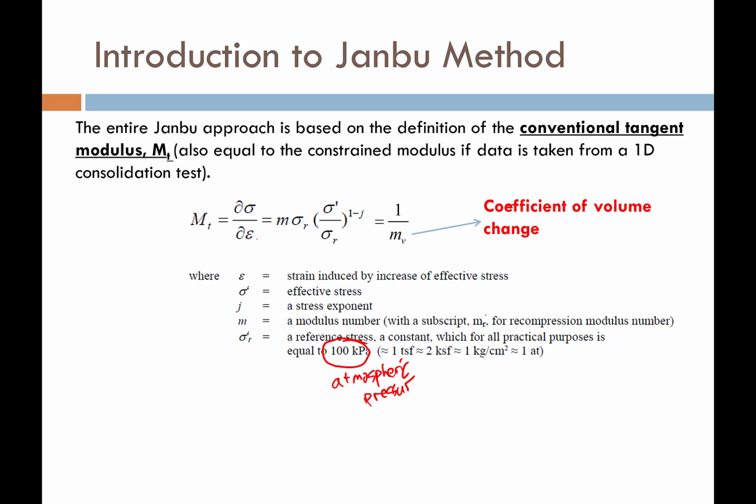Yeah, that m sub v, like we said, that's the coefficient of volume change, and that equals the change in strain of the soil divided by the change in stress.